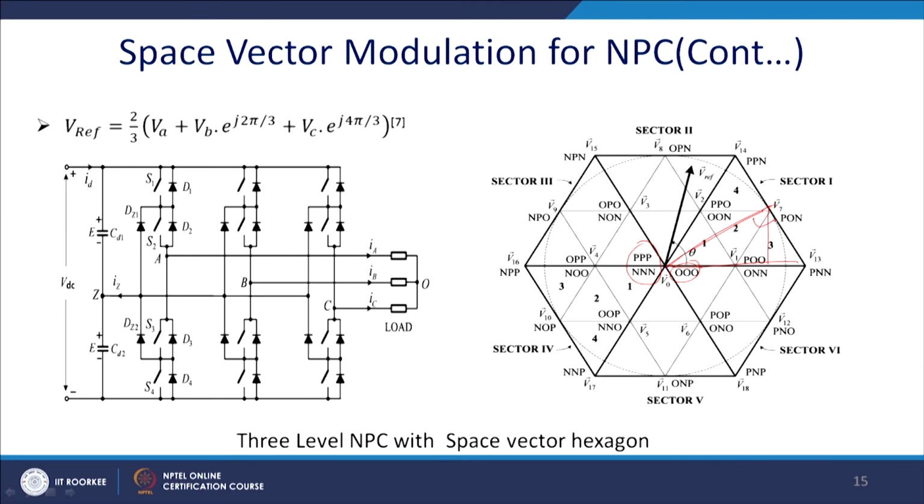So, that magnitude is essentially the radius, and that radius value is your VDC, and this much magnitude will be for the 2 VDC. These vectors are called half angle vectors, and this is called the half voltage or the small vectors in some notations. So, what happened here?